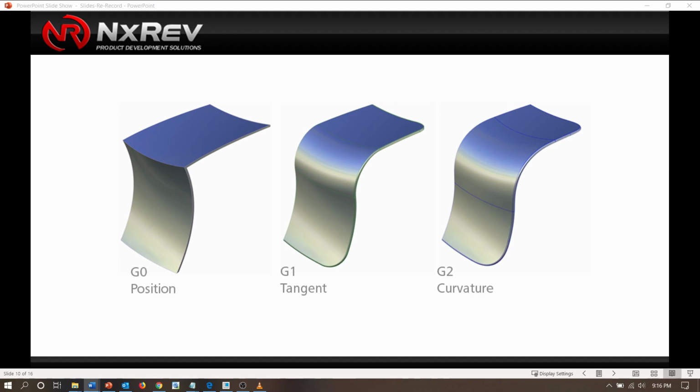And in the CAD world, this is the domain of surface-based modeling commands. Now, the primary benefit for curvature continuity is the ability to control smooth reflections across multiple surfaces. So you become able to make sure that you do not see any unwanted bumps or misalignments in your finished product. So you have more control. Okay.